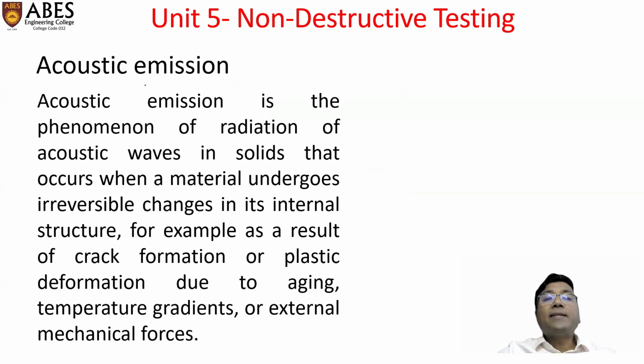Another type of non-destructive testing is acoustic emission. So acoustic emission is the phenomenon of radiation of acoustic waves in solids that occurs when a material undergoes irreversible changes in its internal structure. So whenever stress is applied to a body or to a material, there is a change in its internal structure and irreversible changes happen.